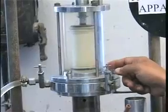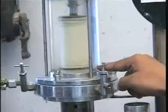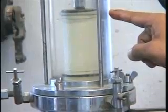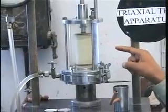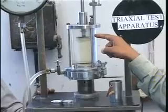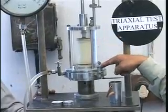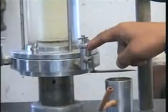There are a couple of O-rings, and you can see one dark O-ring at the bottom, and the top O-ring is actually covered by the membrane in this particular case, and there is a brass cap through which the load or displacement is applied to the sample, and there is a bottom platen also which is covered in this particular case by the membrane.